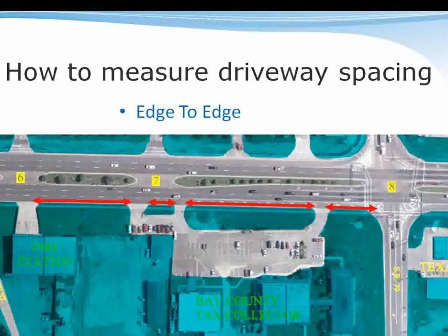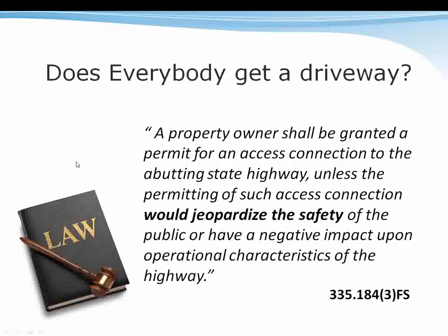The way we measure the spacing of driveways is through measuring edge to edge. So it is measured in this fashion. Now, you saw the standards, and the question always comes up, well, if my property is shorter than those standards, will I get a driveway? And the basic, simple answer is yes.